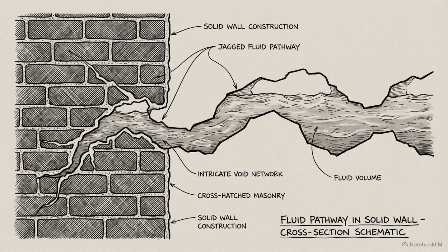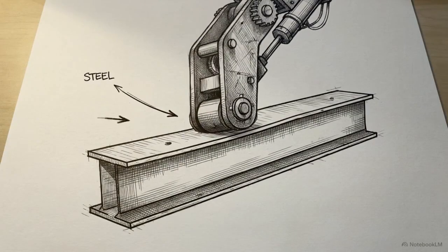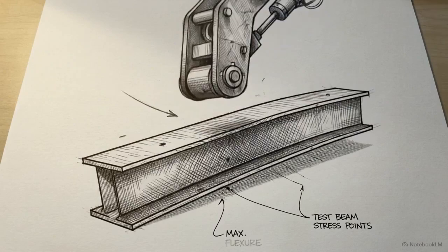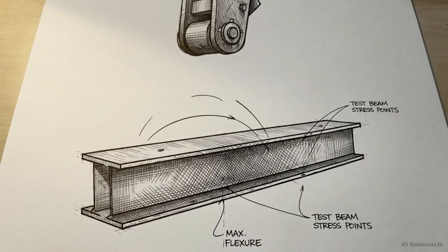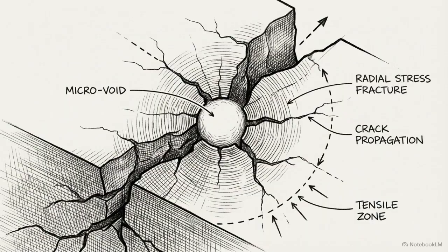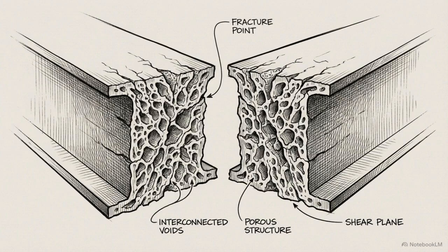Shrinkage porosity is particularly destructive for pressure-critical parts. Because these jagged voids are interconnected, they create direct, continuous pathways for pressurized fluids to leak through the solid cast wall. Even microscopic gas porosity drastically reduces a component's fatigue life, the number of stress cycles it can endure before failing. Under repeated loading, every microscopic bubble acts as a weak point waiting to rupture. A perfectly engineered phase matrix is functionally useless if interconnected porosity severs its macroscopic continuity.